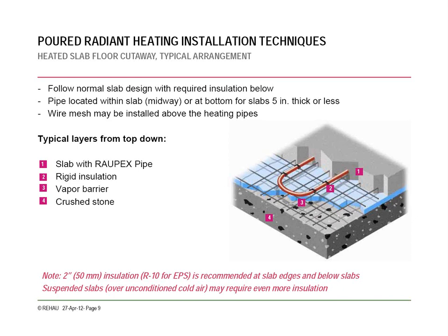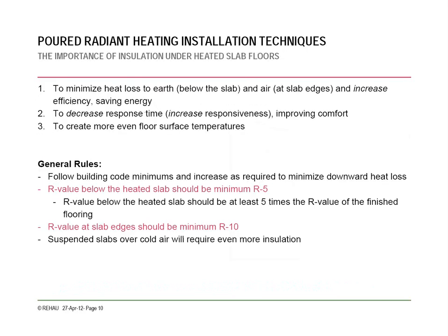This is kind of another look at the same thing. I'm going to skip through some of these slides just to save on time here. It's very important to insulate below the slab if at all possible. In certain cases, especially with snow melt with pavers or asphalt, where drainage can be an issue, we usually do not use insulation. But especially in a heated slab indoors, you always want to insulate below and on the edges if at all possible.